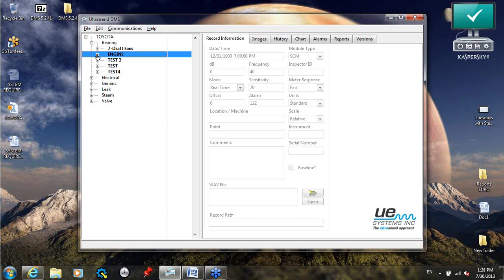So you need a piece of paper and a pen, and the walkthrough should be pretty even flow. What I mean by even flow is you want to start on one end and just go in a straight line and follow the flow of the machine. So if we're at a conveyor belt, we want to start at the very beginning of that conveyor belt. Either choose the left side or right side. It doesn't matter which way. You want to start on one end and just follow it all the way through until you reach the other end of the conveyor belt.